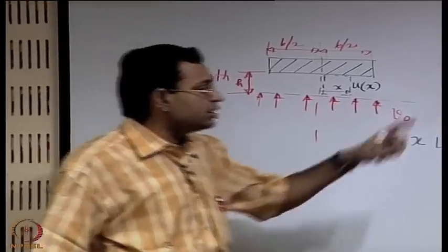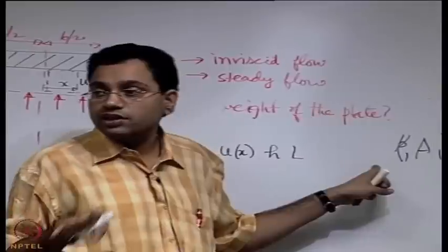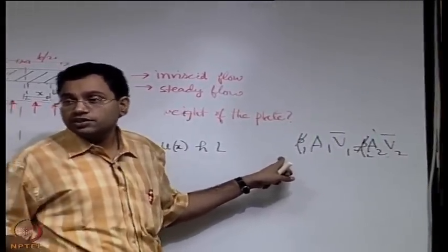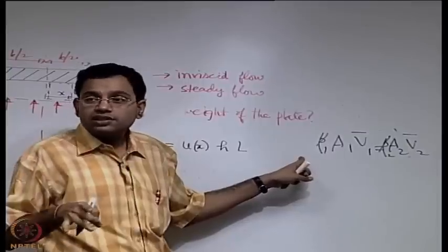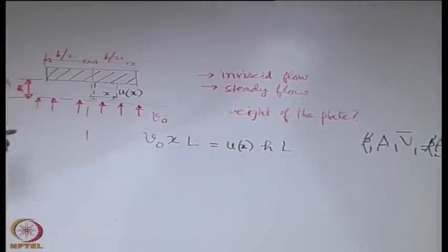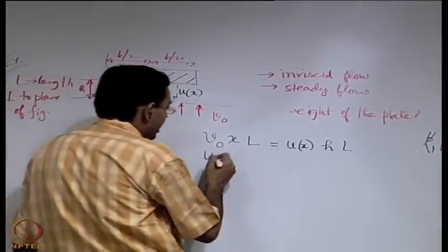So whenever we consider rho to be a constant, we specifically say that rho is a constant. Incompressibility is not good enough to ensure that rho is a constant, but if rho is a constant, it has to be incompressible.